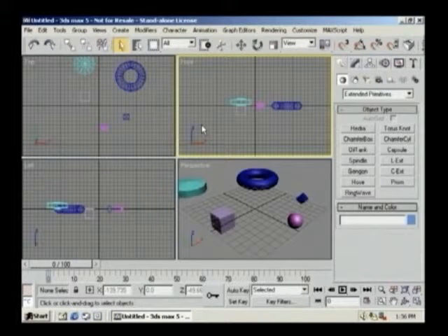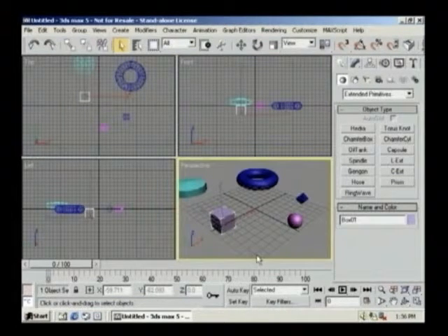As you create and build a scene, to help you stay organized, it's a very, very good habit to get into naming your objects right away. Now, 3ds Max will give each object a default name and a number extension dependent upon the quantity of the certain object that you create. So if you create 12 boxes, you'll then have a box named Box 01 and all the way up to Box 12. And when you need to select one of these boxes by name, it's going to get quite confusing because you're not going to be sure which box was created when and what number. So naming your objects is very important, and it's very easy. You just select the object, you click in the name field on the command panel, and then you can type in the name that you wish. That's it.